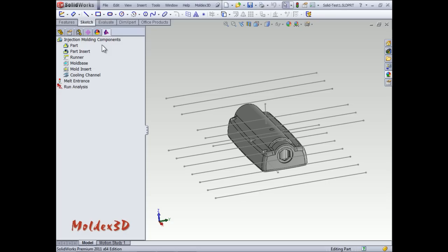As you can see, Moldex3D eDesignSYNC provides a step-by-step workflow to guide our users to complete the pre-processing efficiently. For this model, which is a solid part model, there are two kinds of line structures, runner lines and cooling channels. We will set the part material properties first, and then show a step-by-step setup for the 3D pre-processing of the runners, mold base, and cooling channels according to the 2D line structures. Now we will set up the part material.